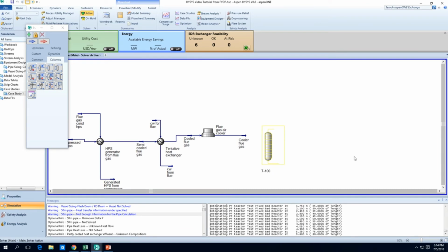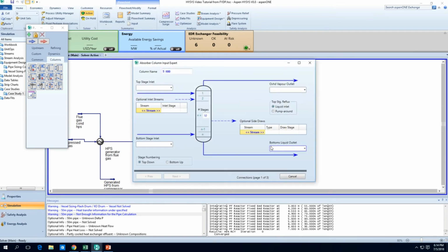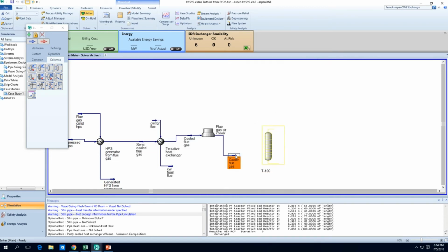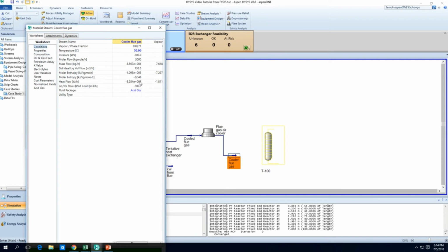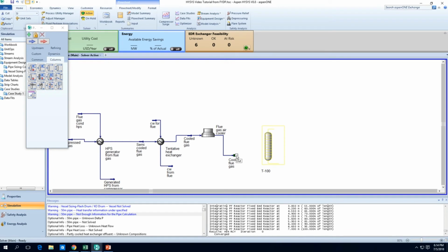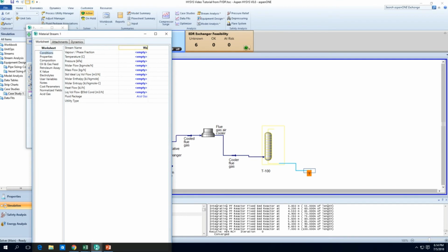So this is the first of many distillation columns you'll probably use, or absorber towers. So this is the absorber, and as in every absorber, you know, the gas will come from the bottom and the liquid will come from the top. So there's a gas and liquid mixture in here because there's actually some water. There's a vapor phase and a liquid phase, aqueous phase. So some of it will have to come out as water. So we'll call this wastewater out. Water will go from the bottom.